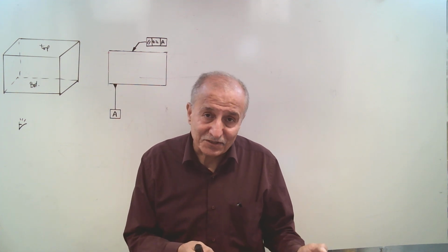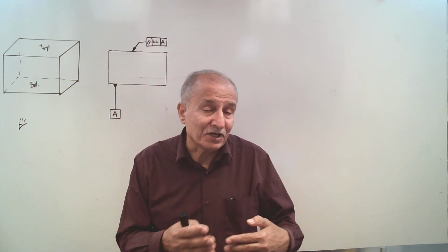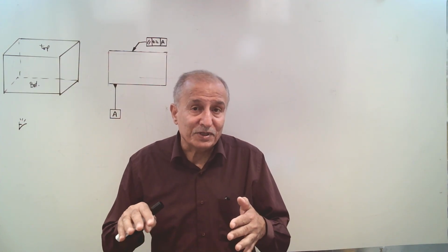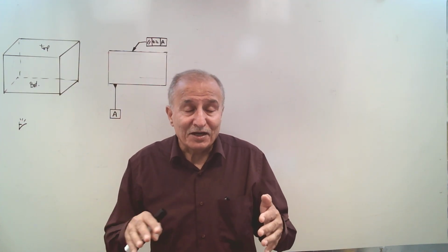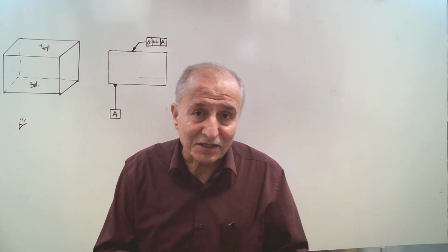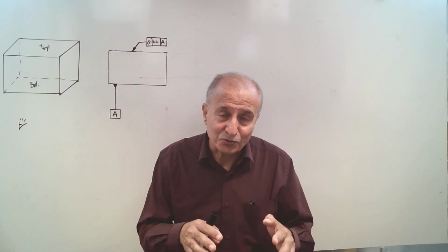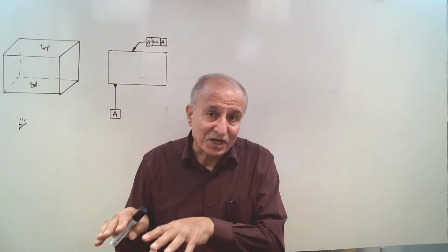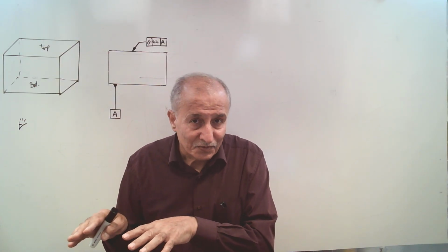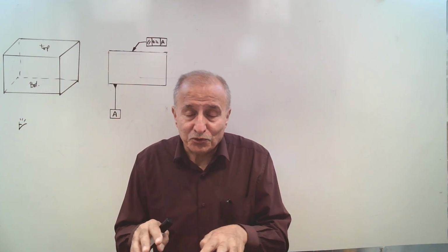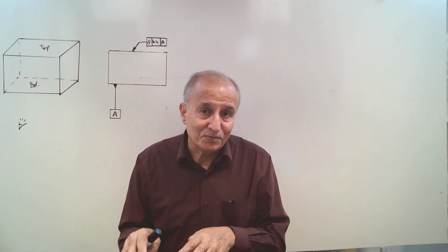For flatness, it's the same. Parallelism indirectly controls flatness of the surface because the surface must lie within a tolerance zone. And all top high points and lower points also must be contained in the tolerance zone. In this case, you are indirectly controlling flatness.